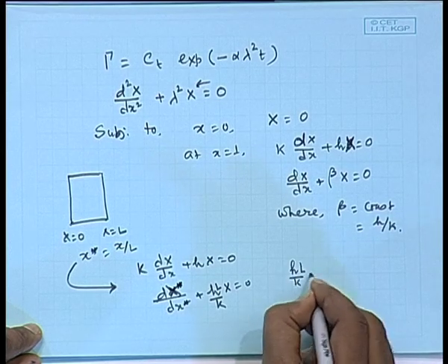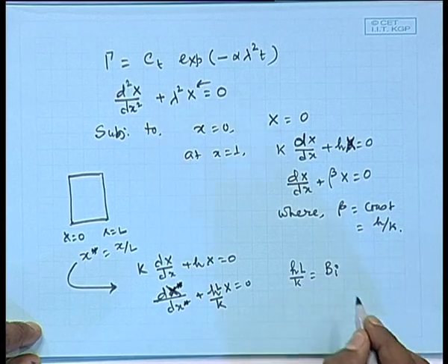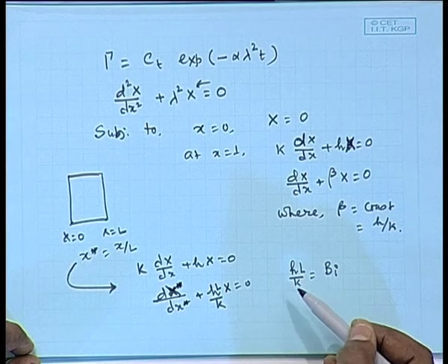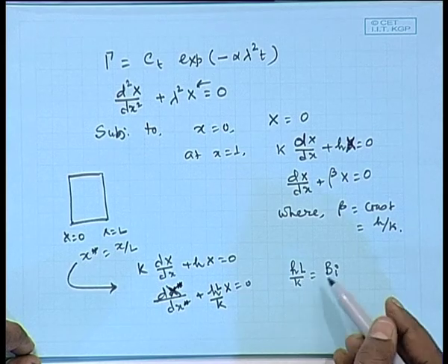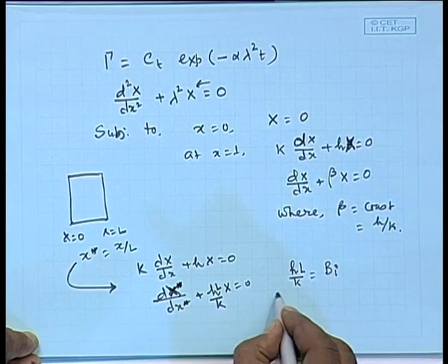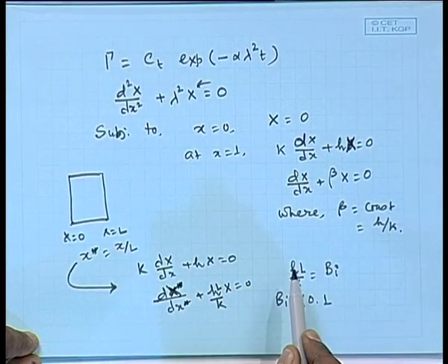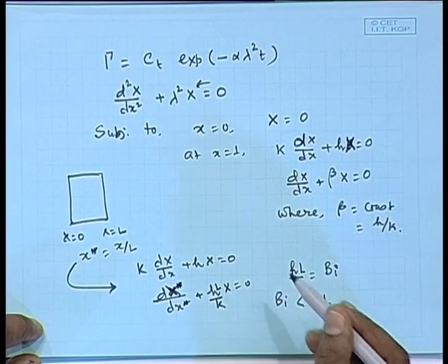This is a Biot number. Biot number, it is a ratio of resistance for the convection and the resistance of conductance. Now for Biot number less than 0.1, you should forget about all this analysis, because there is a lumped system analysis. In that case, no spatial variation is recorded, that is not significant. If that is not so, then this analysis has to be carried out.